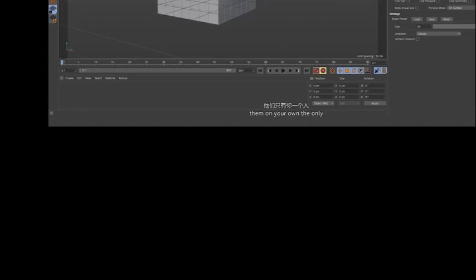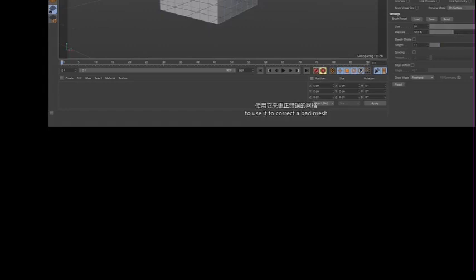There are also sculpting tools for editing polygons which you can use to create or edit the shape of the models. They are in the Mesh menu, the Brushes tab. The set contains all the necessary tools to create simple modifications to models or simple sculpting. They are quite intuitive, and you can quickly familiarize yourself with them on your own. The only thing I want to note is that in my practice I use Smooth most often. It is convenient to use it to correct a bad mesh or irregularities. The rest of the tools are used in some specific cases.